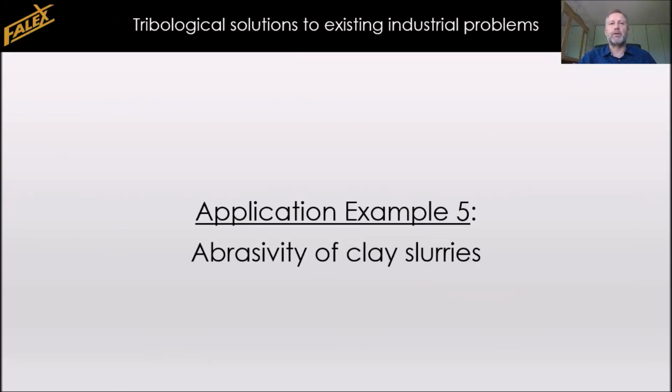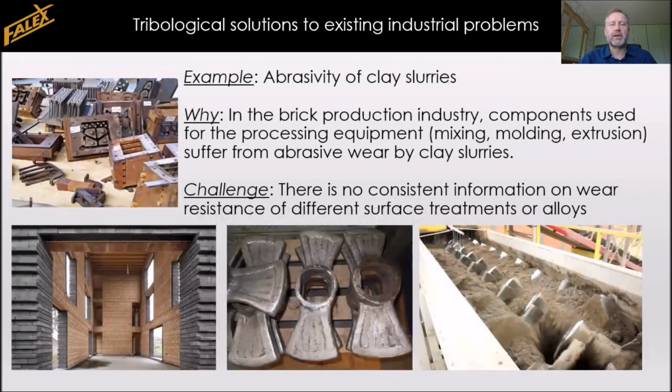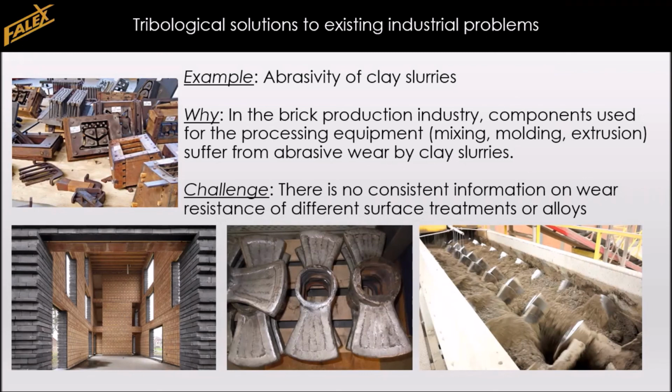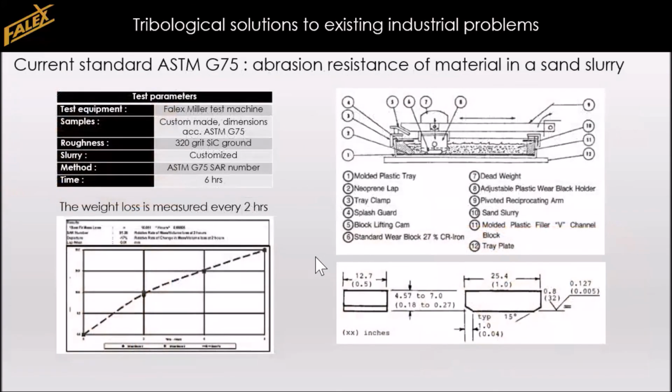In this example, we are looking at the abrasivity of clay slurries. And more specifically, we're looking at a specific problem in the brick production industry, where components are used in the processing equipment and they are suffering from quite severe abrasive wear by the clay that they are mixing and molding. And the challenge that this industry has is they have no consistent information about the wear resistance of different surface treatments or different alloys. So to address this problem, we are starting from an ASTM method.